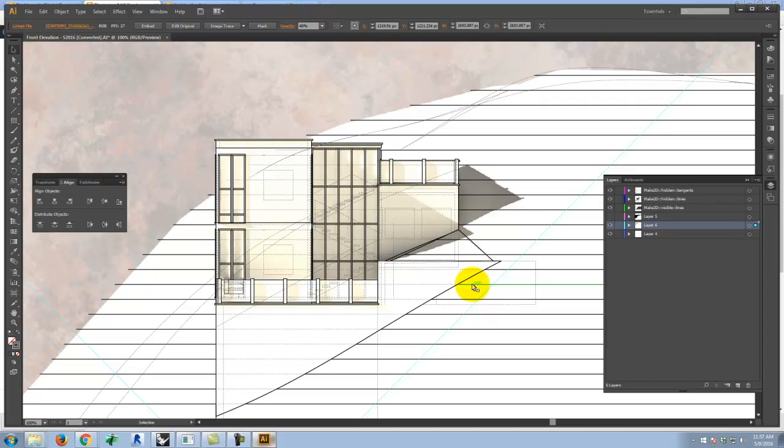I think if you can put these together, you can end up with a really good, high-quality output that you can put on a presentation board without having to manually redraw it in, say, AutoCAD. The nice thing is the same strategy with the Make 2D will work to create an AutoCAD drawing as well. Instead of exporting to AI, you could go straight into AutoCAD if you wanted something to work with there. It's probably not as valuable right now in elevation view, but certainly when we get to plans and sections, sometimes it is valuable to get that into AutoCAD and be able to do that kind of drawing with it.